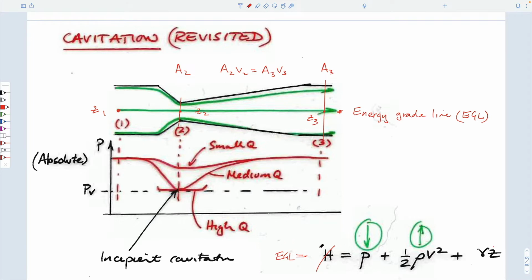And so this means that if we change the velocity of flow, so if velocity 2 increases relative to velocity 3, then by definition the pressure here will decrease. And so if we measure the pressure at point 2 versus point 1, then maybe we can use this value to be able to figure out what the change in velocity is. And not only the change in velocity, but the absolute velocity.